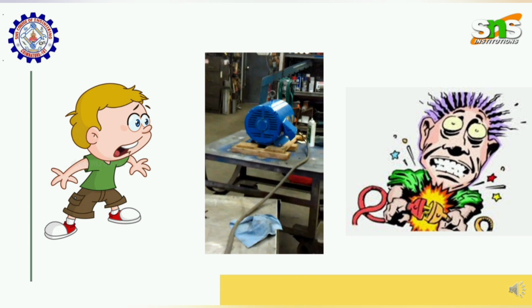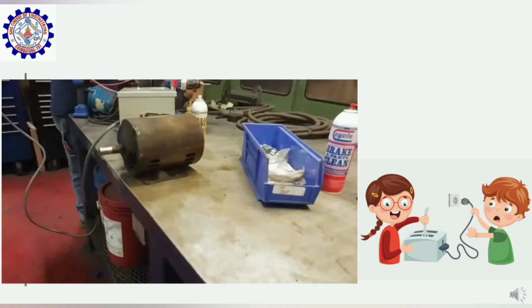The lack of proper lubrication in the motor bearings resulted in increased friction and wear, further contributing to the failure. So, these are some of the common cases where we can see an induction motor failure. In certain cases, this underscores the importance of regular maintenance, proper ventilation, and monitoring of environmental conditions to enhance the reliability and longevity of induction motors in industrial settings.